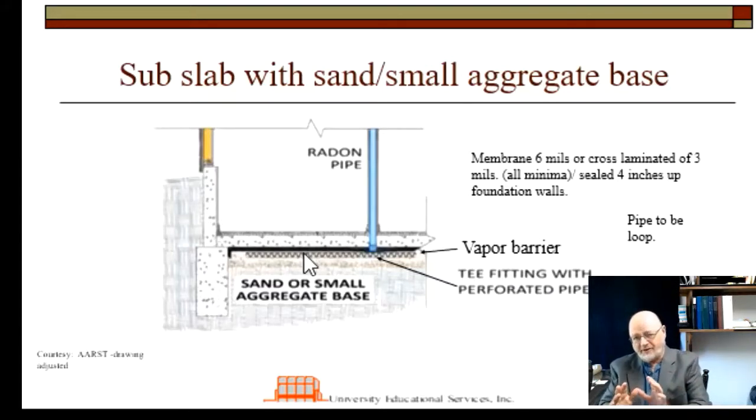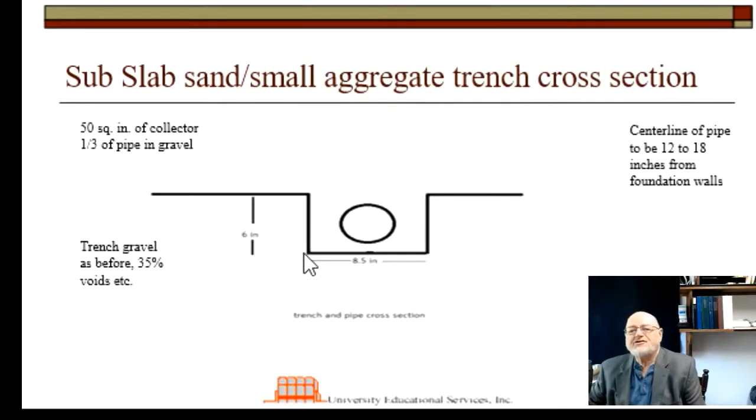I'm going to talk about that a little bit here. As you can see here, here's the trench. I'm drawing one way you could put a trench, some gravel, and put the pipe, embed the pipe within that gravel. This is just one way to do it.